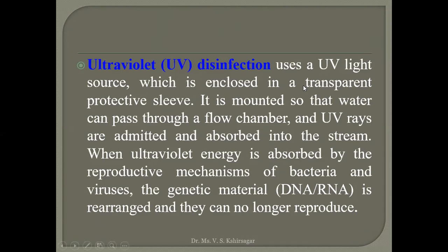Same here. For the disinfection purpose, by using the ultraviolet radiations, we need to use a separate attachment and then a thin layer of water will be allowed to pass through the passage where the ultraviolet radiations are coming.